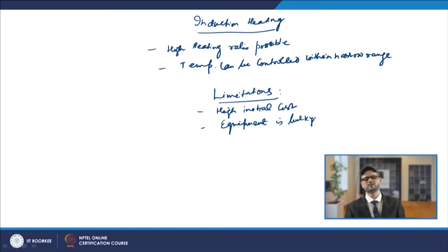And there are other challenges: for non-uniform wall thickness and geometries, there are certainly some limitations. And many times you need extra coils, so extra setups are required. Certainly, those points make it somewhat uncomfortable for the welders or the person who is handling it. So, that is about the induction heating method.